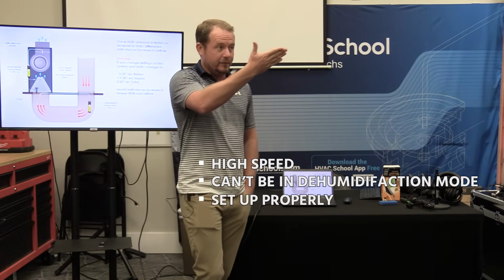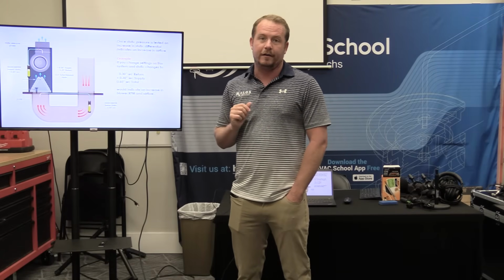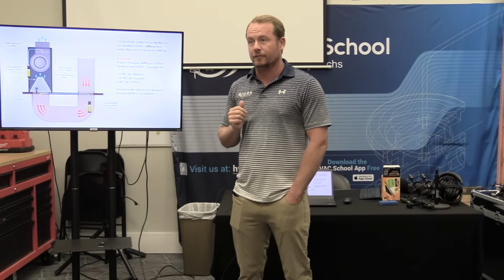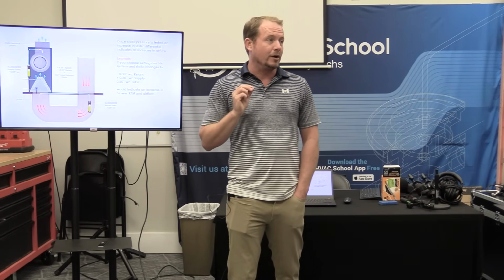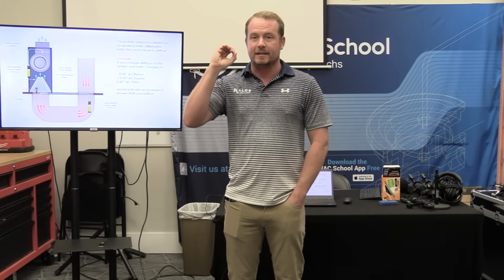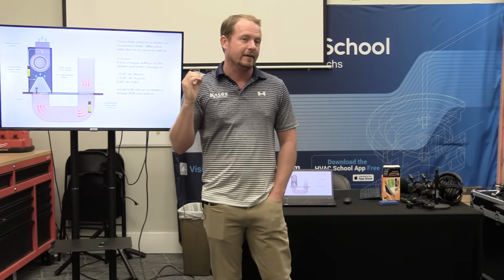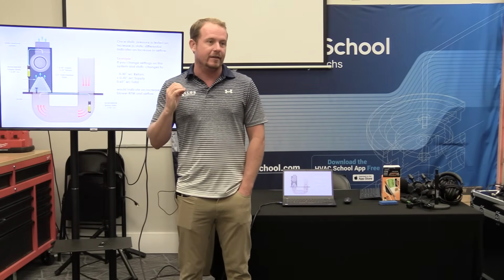So again, if we don't have the taps correct, if we have it set on the wrong tonnage, or inside our Infinity controller or whatever, we have some settings set up wrong so it's not producing full airflow, then static pressure is meaningless. Because again, what is the static pressure on a system that's not running? Zero. And that's a nice low static pressure, right? So it should run great. The point is that unless it's running at full airflow, static pressure doesn't mean anything. So we've got to make sure that it's doing that first.